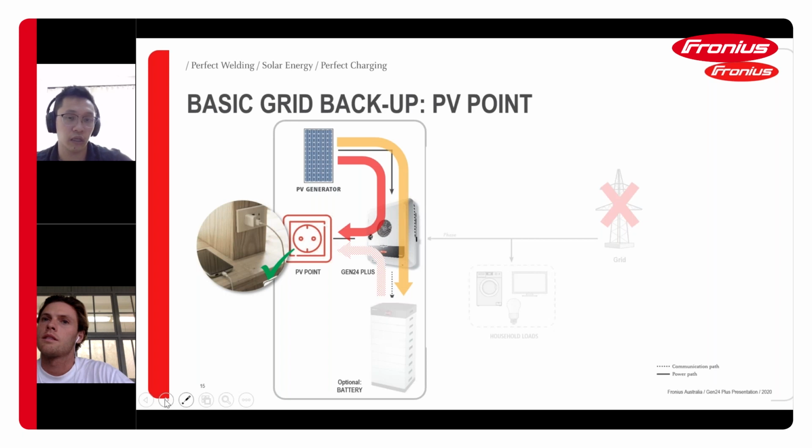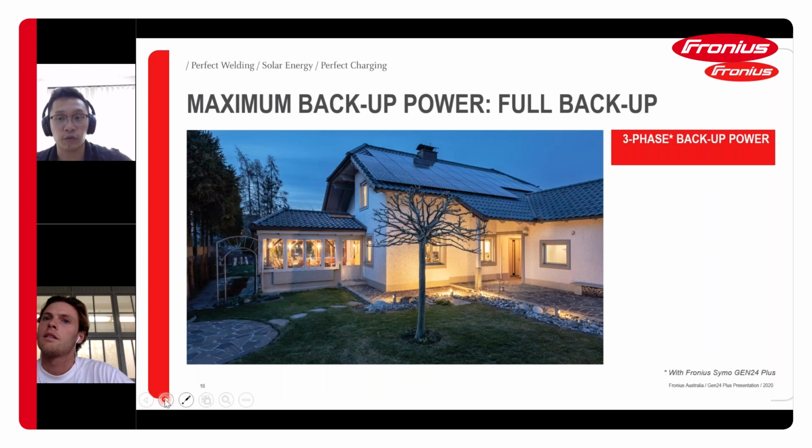You don't need to do a lot of wiring. If you want, you can do a full backup. A 3-phase backup power is only available with the 6 to 10 kilowatt. If you want to do a full backup, it will also work with a single phase inverter, not three phase. Of course, a single phase inverter can't do a three phase backup, but you can do a full backup with a single phase inverter, or a three phase full backup with a 6 to 10 kilowatt inverter.